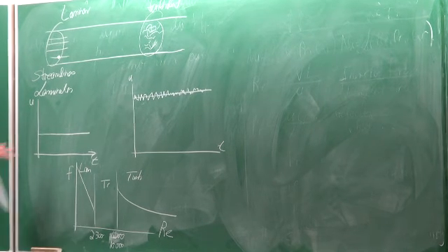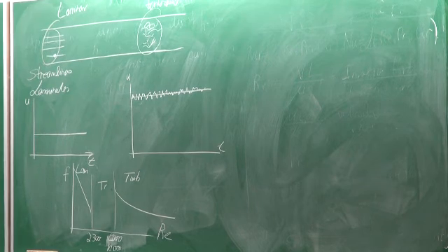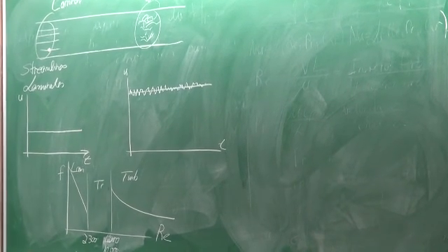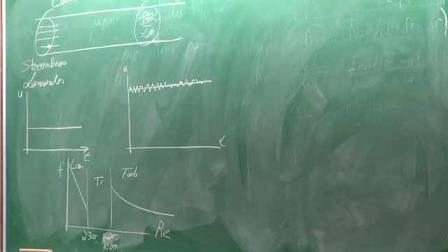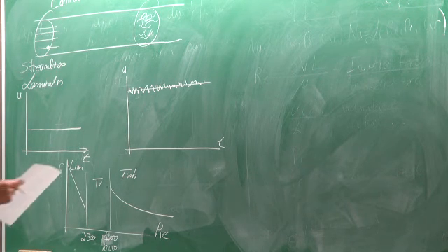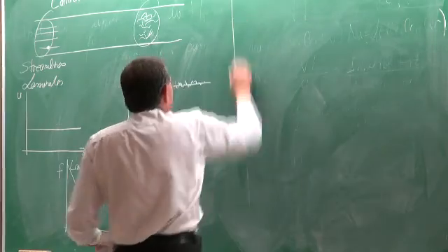However, if the tube inlet is extremely smooth and there are no vibrations in your experimental setup, transition might only occur at a Reynolds number of up to 100,000. Okay, so it's not a fixed value. But in general, you can work with approximately 2,300 to 4,000. Now those are the friction factors.